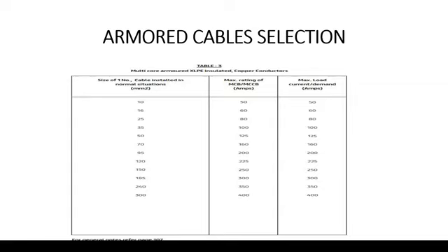So please, this is a very important point, don't make this mistake. Be sure to know which type of cable is specified in your project. If you have the choice, I advise you to use the XLPE. The increased cost for XLPE insulation is accounted for in the reduced conductor cross section which you are going to use. So in this case, I'm assuming the XLPE insulated cables, table number 3 in the DEWA regulations.